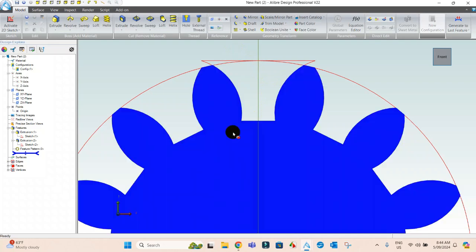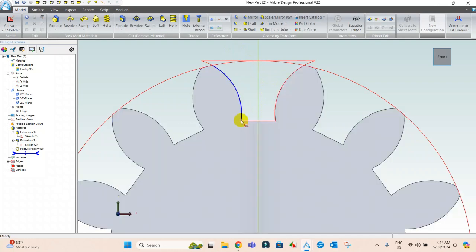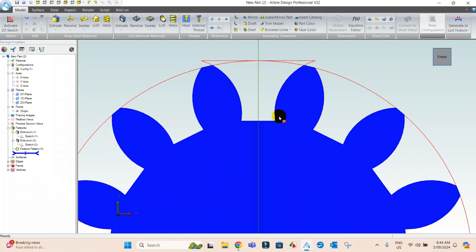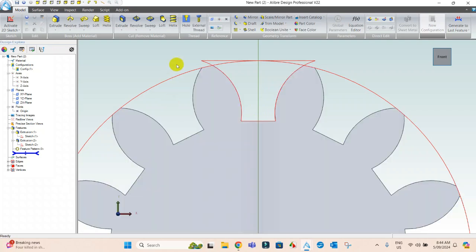Remember, I did not put in the radius in the corner that this gear would normally have, as normally a 0.25 radius. That would come up to around about there. So at about a 12 or a 13 tooth, this is a cutter that will do a 12 or a 13. There would also be a radius at the bottom there, and this would most likely not undercut. That's why anything less than 12, you find there's all sorts of problems with undercutting of the teeth, and you can't necessarily make that particular gear.